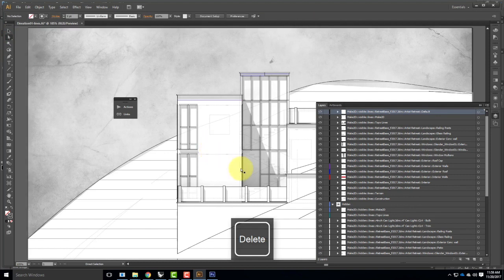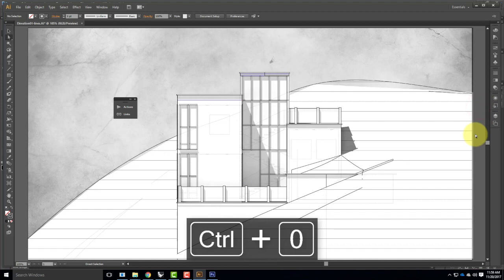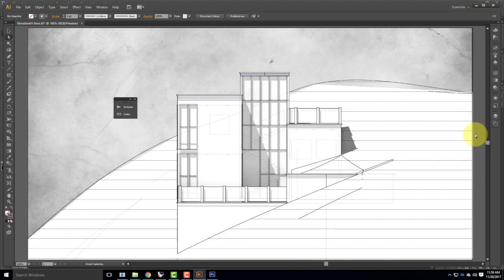Okay? So the idea here is that from our Rhino model, we were able to relatively easily create an elevation view that has a little bit of shadow behind it, but that is fundamentally a line drawing. It's not a rendering anymore. It's a line drawing. So we will be going back through these steps over and over again because we're going to do the plan and we're going to do the section. The difference between those is we have to cut the building. So it's essentially the same thing 3 times. We're just cutting the building and changing part of it to see-through. So it's a combination of last lecture, 227, and today's lecture, 228.